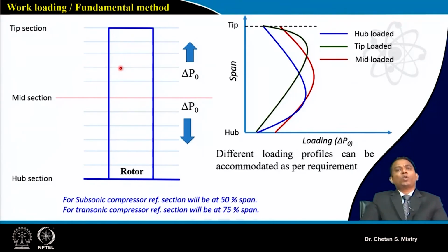Okay. So overall, if you try to recall, we have discussed all the design approaches available in the open literature which people opt for in their designs. We have discussed the exponential design, the free vortex design, and the constant reaction design, and the advantages and limitations of those methods.